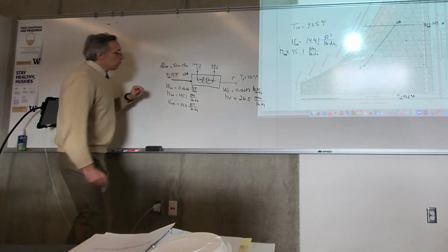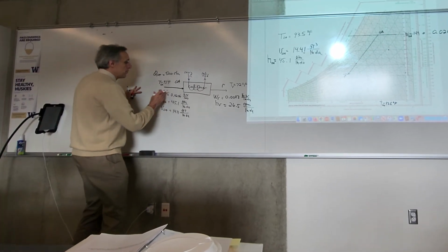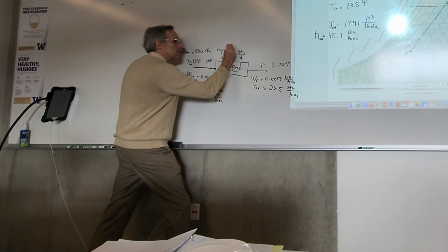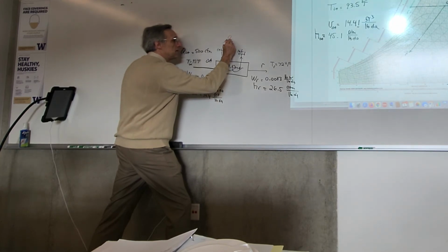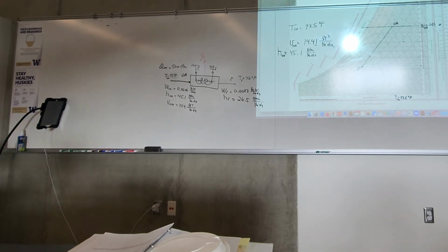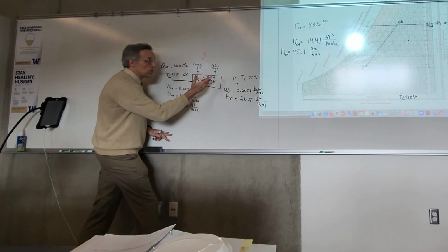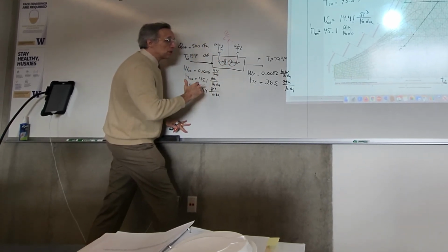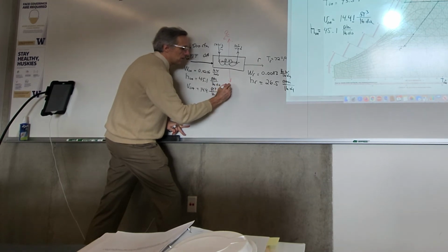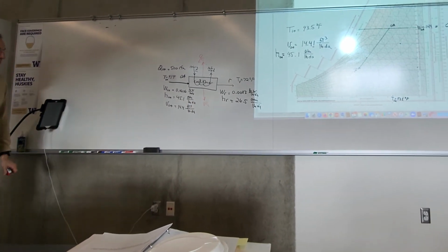Okay, so we want to do an energy balance here. First law balance. So we've got warm stuff coming in. This refrigerant is going to carry out heat. We'll call that Q conditioning. This is the heat that we're removing. And because we are dropping the temperature below the dew point temperature of the water, we're going to condense water out at some mass flow rate C.